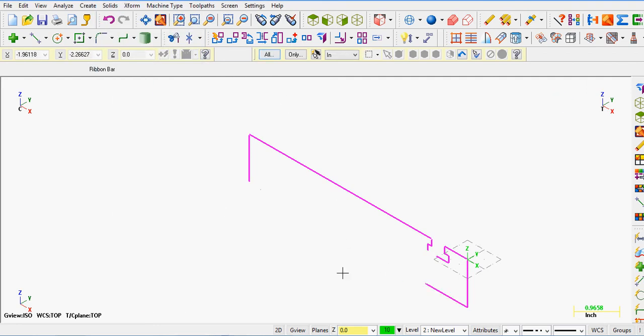Some of the lines disappear. It's not a problem. Simply click Repaint. Okay. You'll notice this has stayed purple or pink. I guess it depends on your perception. To set the color back to the proper color, I come over here and I say Clear Colors.